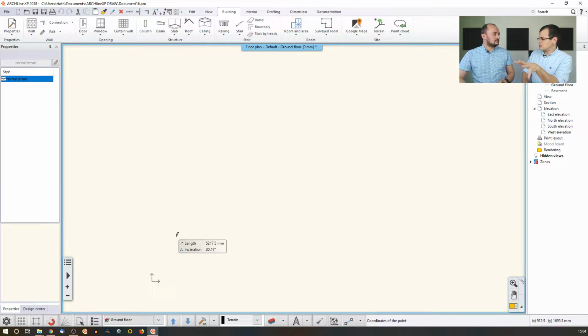This is still in the 2D drawing panel, right? Yes, that's right. Now we are in the 2D. And actually, there is one thing with the terrain. When you would like to set up the points, then you either trace an existing drawing, or you trace the contours of the building or something like that, or you can work with coordinates. If this is a coordinate at 0, 0, you can just start typing, either deciding whether you locate in an absolute coordinate system like the world coordinate system or a relative coordinate system, and then you can decide where this location point is.